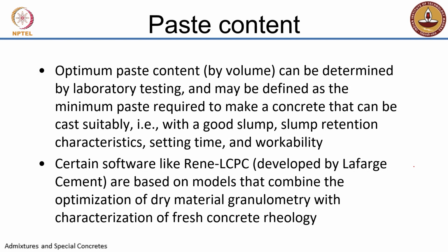Now, as I said, we can do testing of aggregate combinations to determine the void volume and decide the paste content based on that. Or you can just do random laboratory testing and arrive at a mix design which gives you the right level of workability, strength, and so on. But that's a little too cumbersome, and you need to have a good starting point. It's very good to have a starting point which deals with determination of voids content and then determining a paste volume based on that voids content.